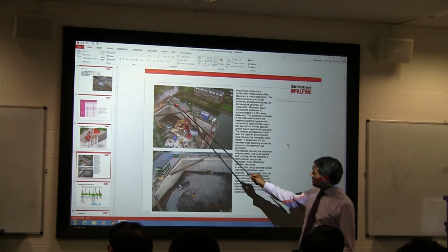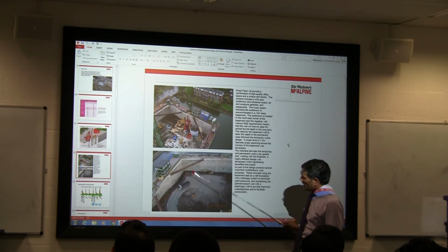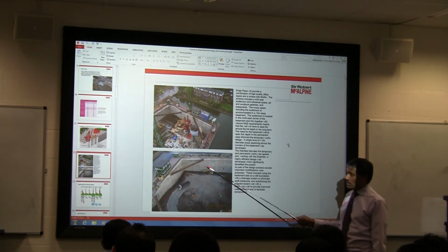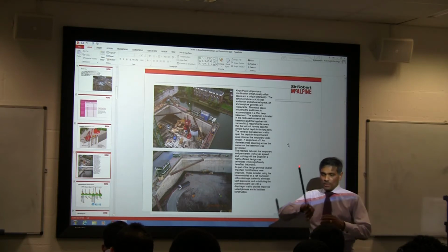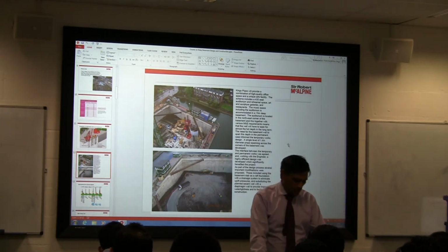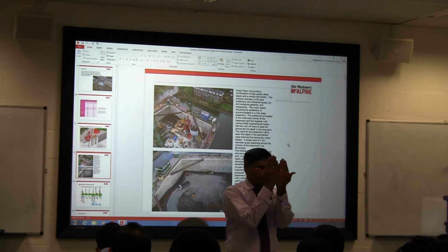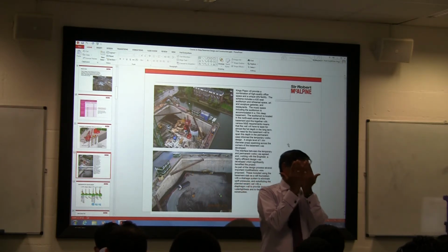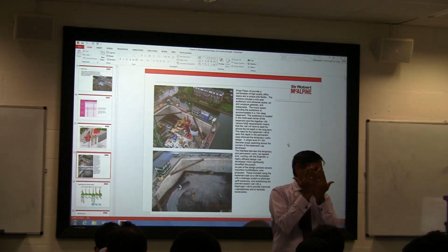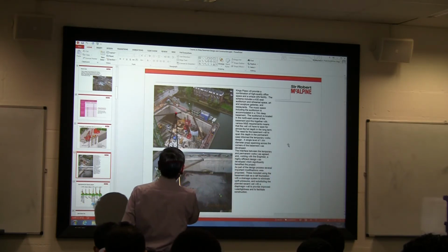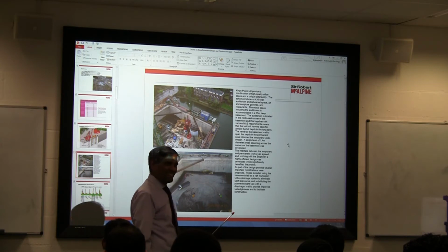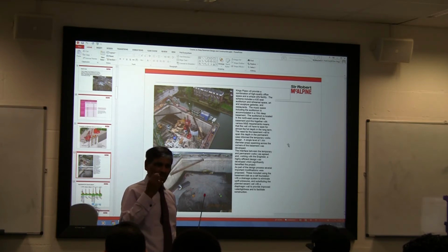So we actually installed the diaphragm walls all around the site, as you can see clearly. You can see the fantastic interlock that we got. Obviously, between the joint, when you do the panel, that's one panel, and there's another panel. Between them, there is a water joint, so that is also nicely interlocked, so the water cannot come through. It's next to the river, and you can see how dry it is. That's the beauty of the diaphragm walls.